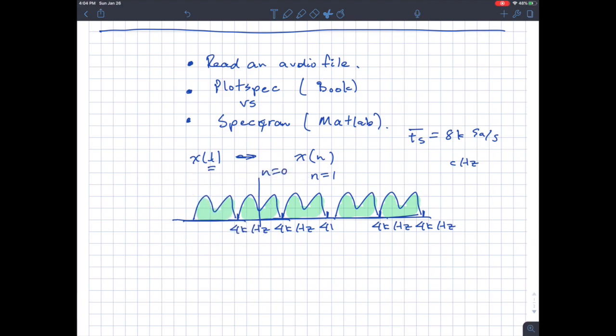All right, so what happens from there is that when you reconstruct the samples to get back into the continuous time world, because we live in the continuous time world, you use a low-pass filter that grabs the zeroth replica. All right, so here's a low-pass filter. We're going to keep all this and we're going to get rid of everything else. Okay, and that'll look like our original signal.